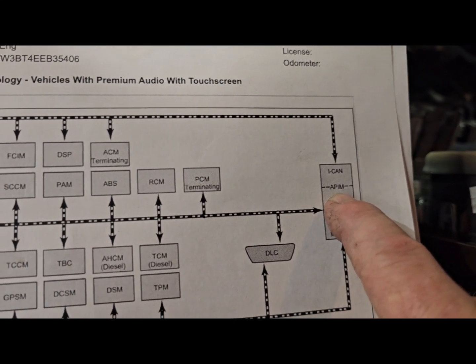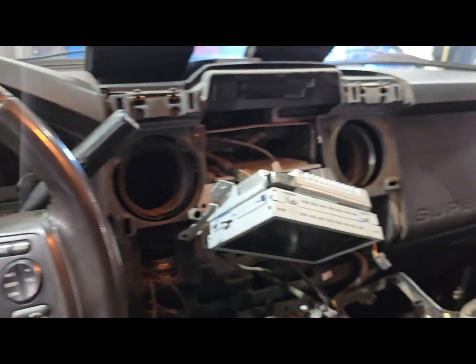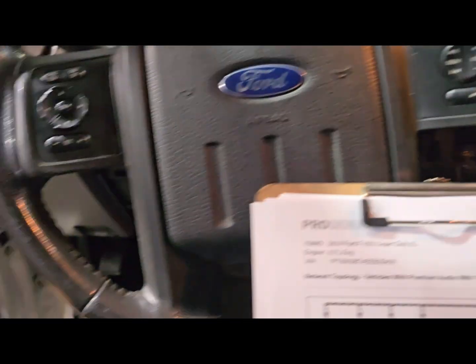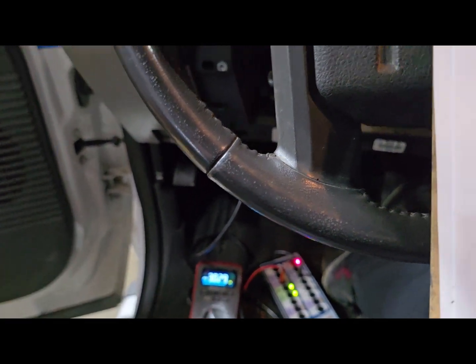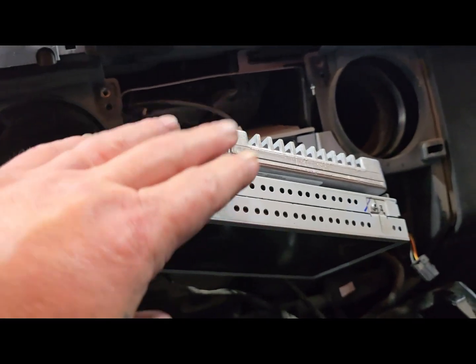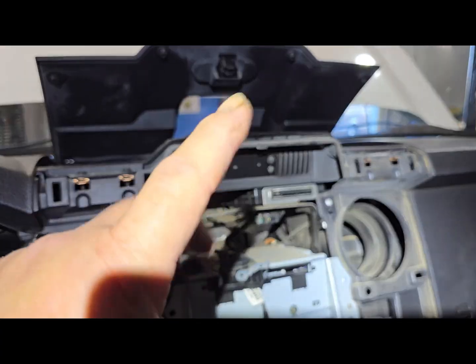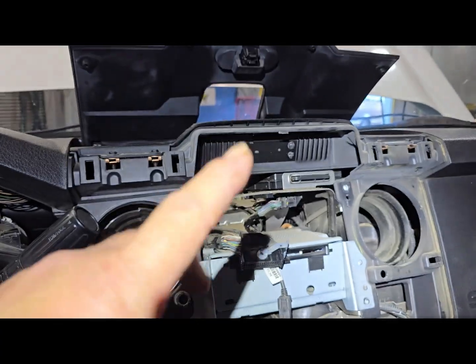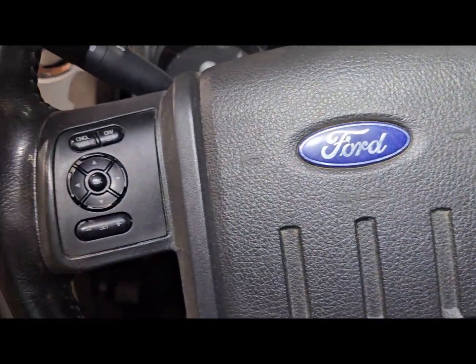Now, I have not started the truck. I have not turned the key on. This is first thing in the morning after I have all of this stuff disconnected. I was just trying to get back my ohm reading on the CAN system. So now I'm going to disconnect the APIM and see what happens. So I know the APIM is bad. That has failed. I'm going to leave that disconnected. We're going to reverse, plug everything back in, and see if we can get a change.